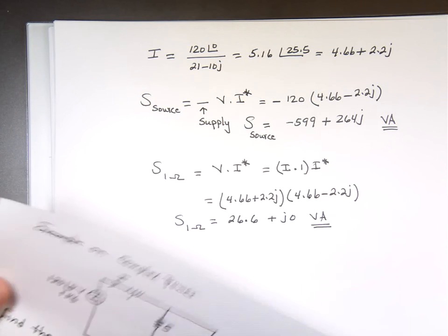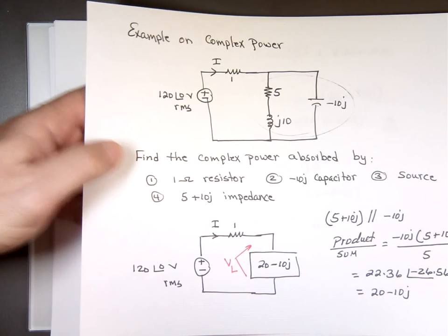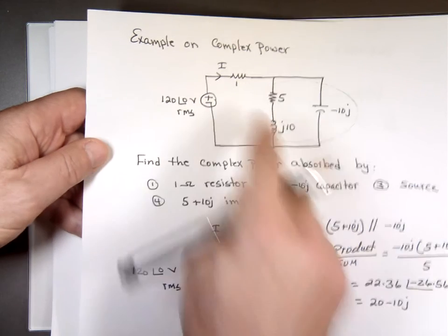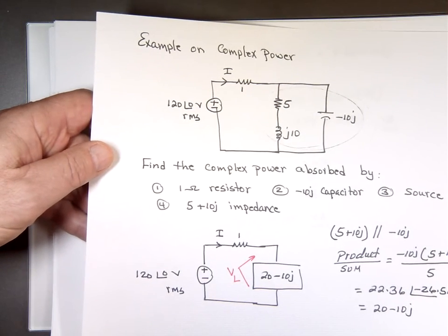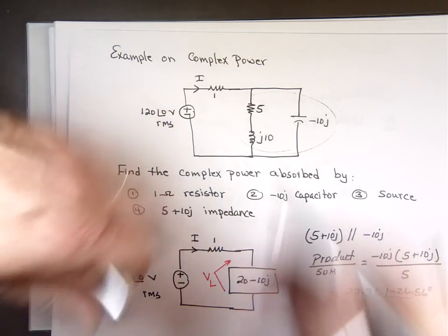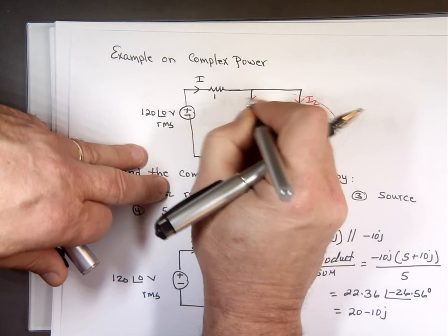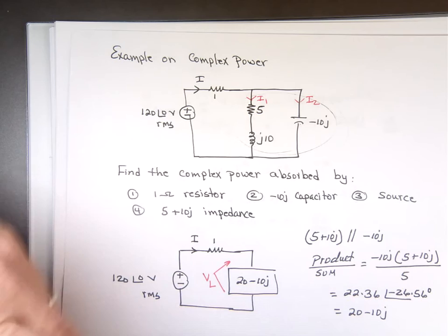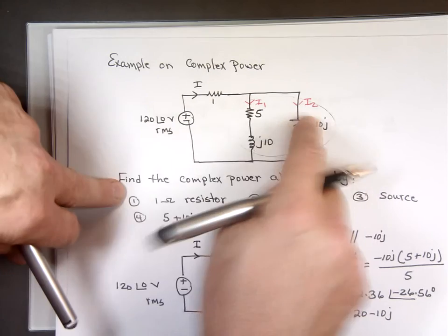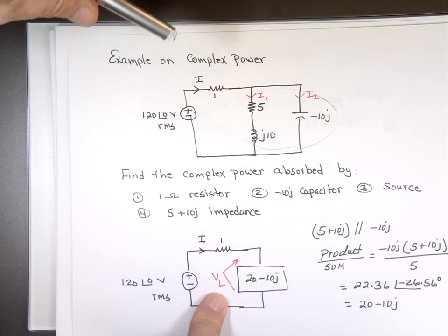Now, these two here, I got a little problem. I don't know the voltage or the current through them. If I know the voltage, I can find the current through them, right? If somebody comes and whispers in my ear, say, the voltage is 17, oh, that's easy then. I know what that current is. And I know what this current is, if I know the voltage across. Since these two are equivalent to this, I can find that voltage VL. Voltage division. Going back to circuits 1.